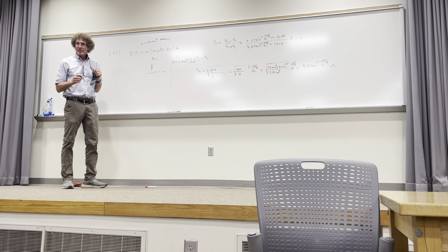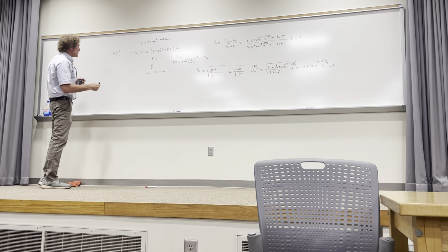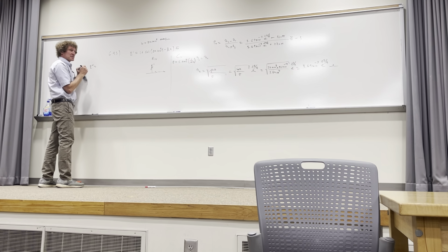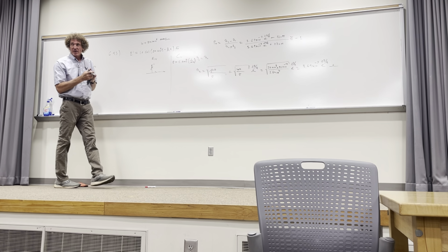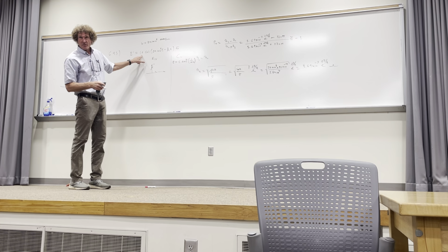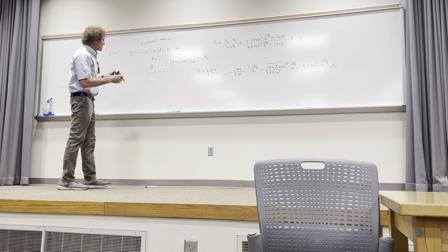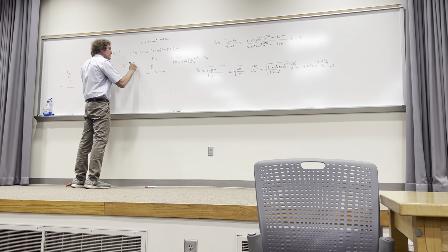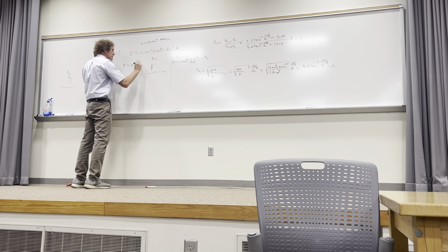Do y'all follow me? So that means if we want an actual equation for the reflected field, it's about equal to that, with one caveat. It'll be minus, right? Y'all follow me on that? So if we put this incident field in a phasor form, let me do it that way. E phasor would be 10 e to the minus j beta 1 z in the a_x direction.